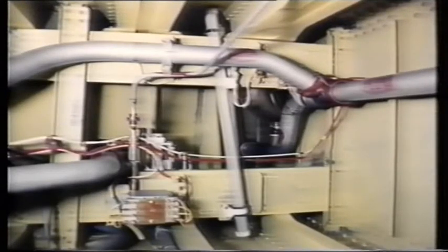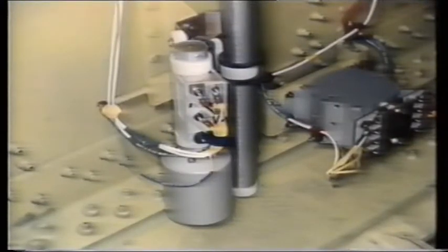Tank units are mounted in each tank. They measure a capacitance that varies with the fuel level and dielectric constant. Compensators are mounted in the lowest point of each tank and are used to determine the fuel dielectric constant. The FQIS processor uses this information to calculate fuel on board.